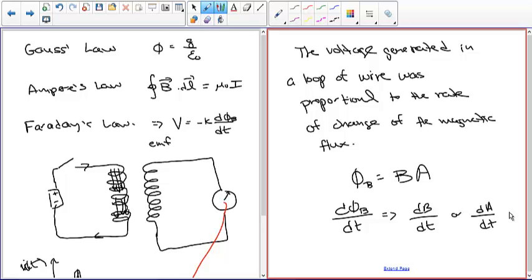So if I had a permanent magnet here, a north pole and a south pole here, and then I had some way of rotating this thing around, and measured the voltage in this loop, it would actually be a sine wave. You generate an AC voltage by having a fixed magnetic field and rotating this thing around.